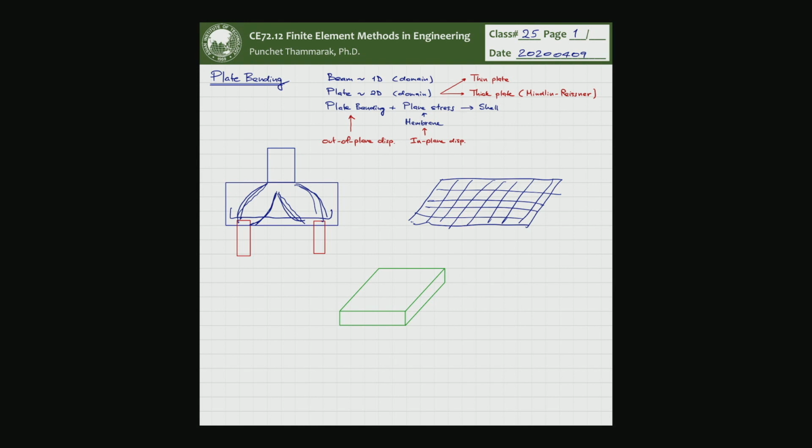The point is that to do so will be conservative, because the actual load transfer is better through the strut and tie. Strut and tie gives you better stiffness, and the load carrying mechanism is not as brutal as the plate bending.